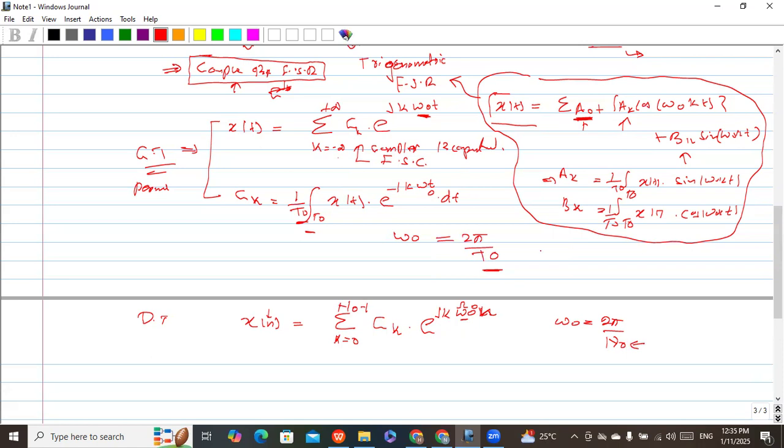In a continuous time signal we know the period. How to find the period? Maybe you can simply remember this: if it is a continuous time repeating signal, we select two consecutive repeating points and calculate the time difference between this point and the immediate repeating point.